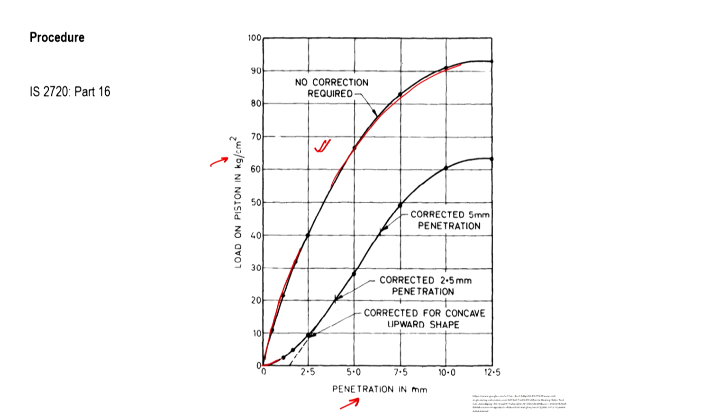But if you see a concavity at the beginning of the graph, as you are seeing in the second graph here, which means it will be more of an S type curve, then you have to apply some correction. So, how will you apply the correction here? I will first locate the point from where the straight part starts and I will make a tangent. I will make a tangent here and I will mark this point. So, this will be the new 0 point, which means I have to shift the axis from here to here. Likewise, all the values will be shifted by an equal distance.